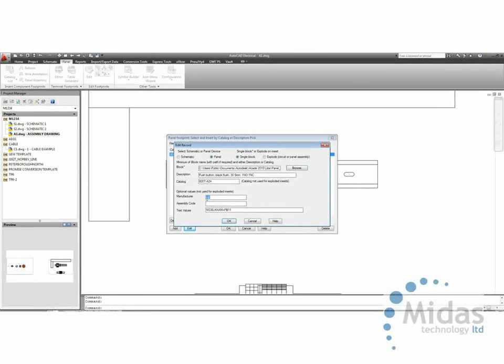You'll also notice that the manufacturer has been defined, but also the WD block name is going to equal PB11. Now you might not recognise what the PB11 is, but if this was a vertical switch it would be called VPB11, or if it was a horizontal it would be called HPB11. We don't have to put the V or the H in this value.